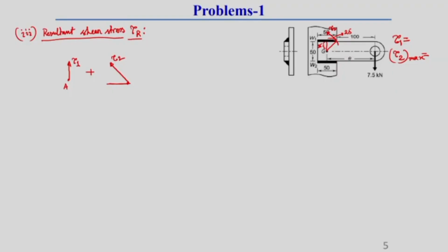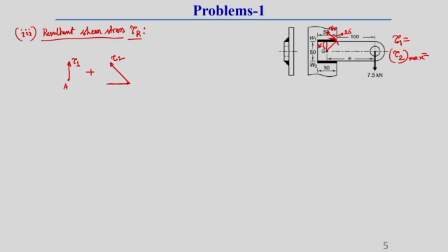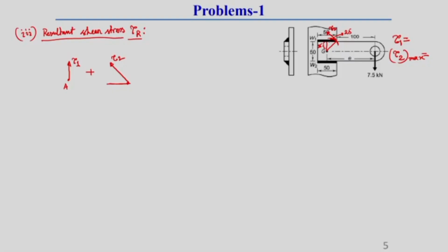So, once it tries to rotate, that means in this farthest point there will develop a curve-like rotational displacement, correct. So, in this farthest point in this curve, once we draw a tangent, that tangent direction represents the shear stress direction. Okay. And as the tangent represents the shear stress direction, we know this tangent at a point is always perpendicular to the radius connecting that point. So, these things you just should keep in mind.